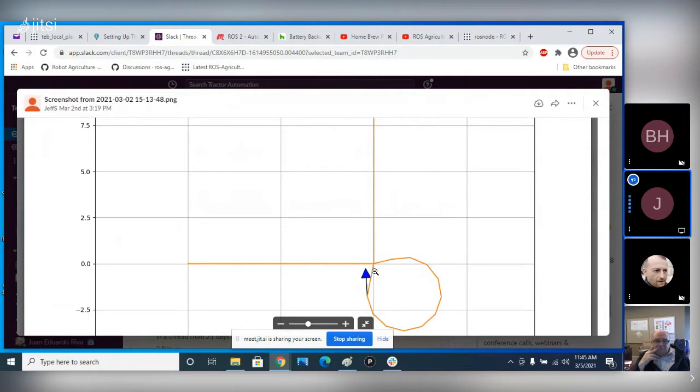So what it does, in order to get there, it says, oh, well, in order to do that, it has to start. Dubins uses either 3 curves or 2 curves and a straight line. There's some combination. It always creates 3 segments. So in order to get there, it starts driving. It has to make a complete loop in order to hit this going in the right direction. So I'm going to go back through that same point, but at a 90-degree angle.